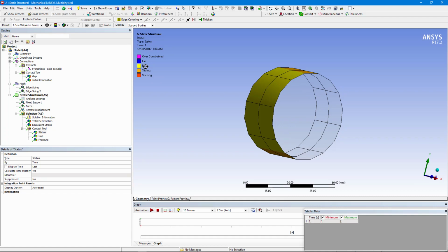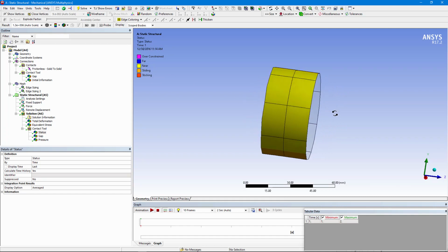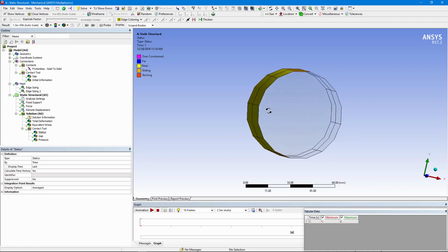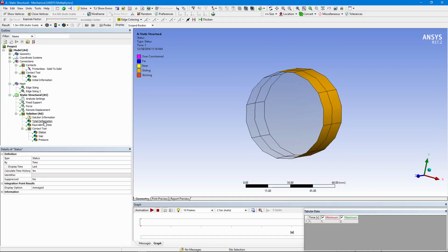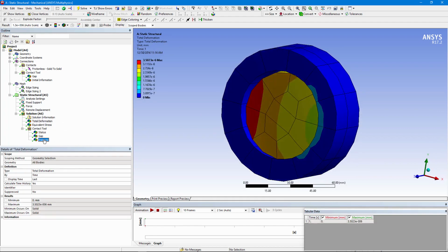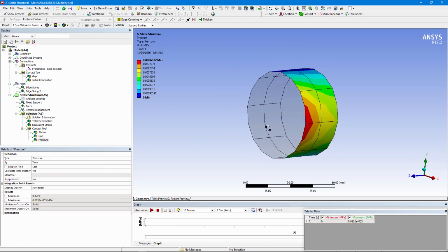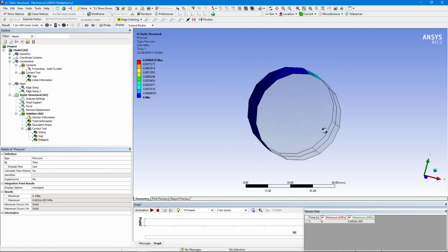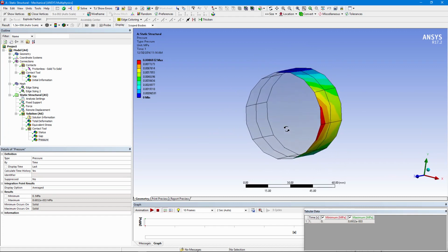And on the left we're near. We're inside the pinball radius but we're not touching, as is implied by this look at the displacement. I can also check my contact pressure and see that because of the load and displacement constraints I put on the model, that's the contact pressure on the contact side for the model that I set up.